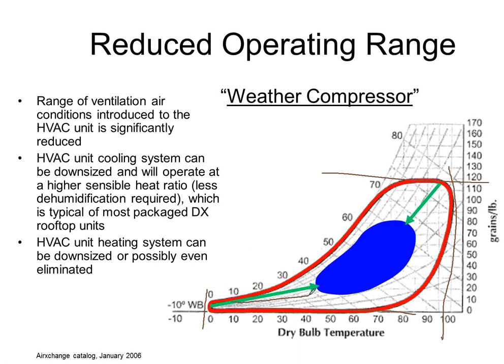Well, if I'm able to preheat, pre-cool, pre-dehumidify, and pre-humidify my air, I don't care about the red blob anymore. Now I'm sizing my rooftop for the blue blob. Blob's a technical term for those that don't know. So I'm going for the blue circle there.